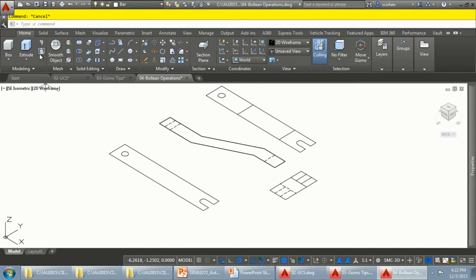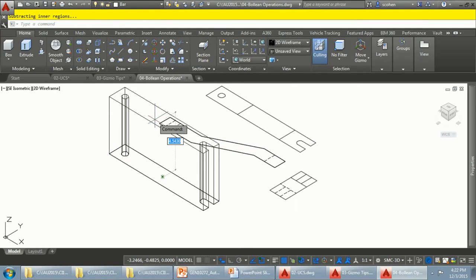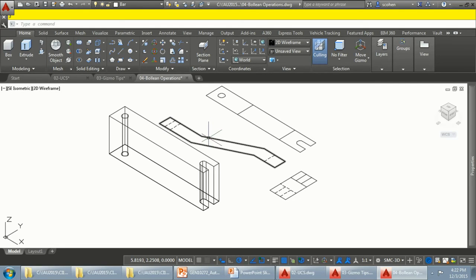So you could use press pull right here, or Control Shift E, and you just hover over and then click, and it automatically press pulls. Control Shift E. It used to be Alt in like 2009, and then all of a sudden, in one version, they just took it away. We're like, where's Alt? And then they made it Control Shift E. I don't know why, but whatever. So I'll just type 3, enter, and there's my height. Now, the next thing I want to do is extrude this side view through it to get it so I can make this one solid. So I'll just pick here.